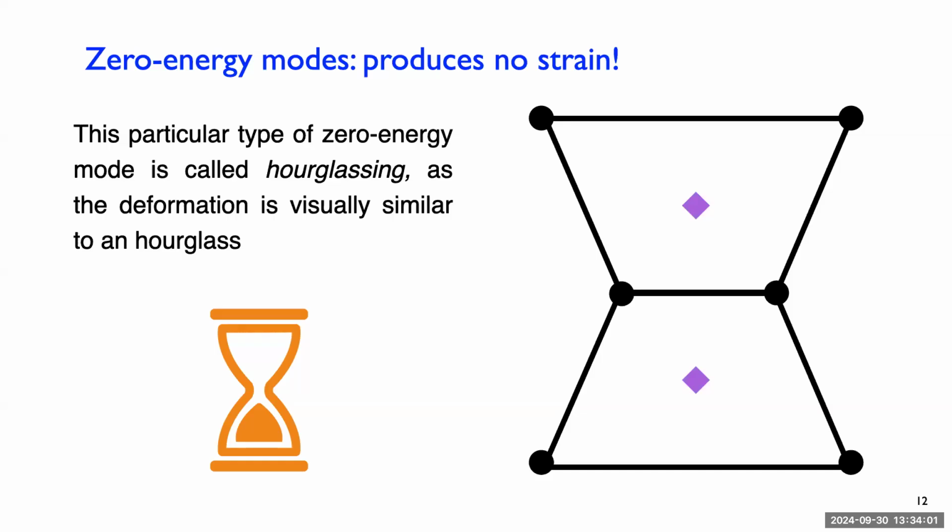If you look at your overall mesh, you'll just see it goes in, out, in, out, in, out, like this. It's called hourglassing because it looks like an hourglass. Visually, this looks like an hourglass, and they often call this hourglassing in finite element literature, and they call it hourglassing in Abaqus. So if you see hourglassing in your model, you need to be careful. You need to do something because it's just nonsense, essentially.